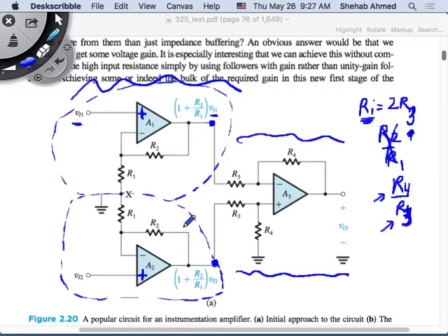So if I have a signal that has my measurement as well as common mode voltage, and I amplify my common mode voltage, what is that doing to my output? It's eating from my ability to send the signal through without clipping it or changing its frequency content, right? So this common mode problem is still an issue that we need to deal with.